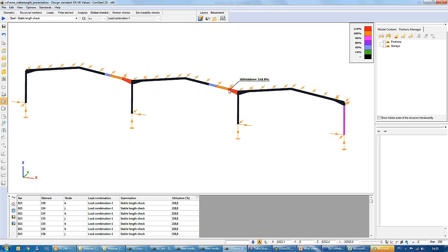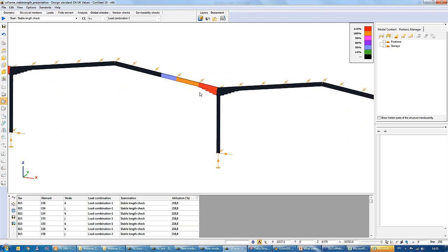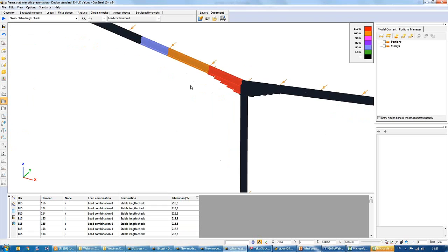At the first step, it recognizes where the plastic hinge is, and it starts to move. The program will check and start to move in one direction and the other direction from that plastic hinge. In case of this column, of course, only one direction, and it will search for lateral or torsional restraints. I mean lateral and torsional restraints too.